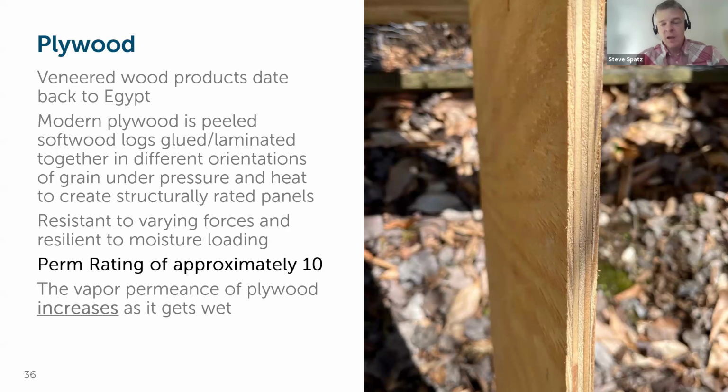because that wood has not been changed from its original form. The next step down from that, as far as vapor permeability goes, but still considered a very vapor open sheathing option, is plywood, CDX. So veneered layers of wood that are peeled off of a log and then glued together to create a structural board is, in this scenario, we're talking about wood that is less adulterated from its original form.